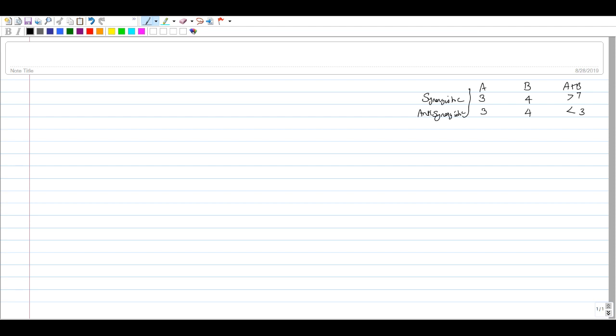Pugarendi has asked what is the use of orthogonal array in robustness. I guess we have enough discussion on the lectures themselves, but the idea is simple. In a couple of lines, if I need to answer, orthogonal array is a template to do design of experiments. It's just a set of experiments, and there is some sort of mathematics behind these orthogonal arrays. For instance, if you go into the lectures, you will understand the concept of balance within a particular column, and between any two columns, the number of repetitions are the same. So those types of qualities are ensured in orthogonal arrays.